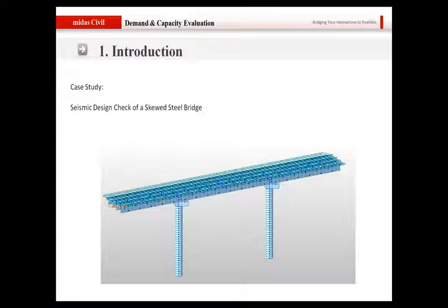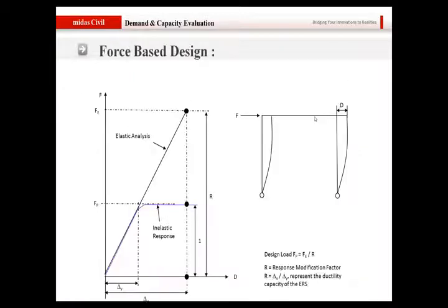For those of you who were present in the technical seminar by Ling Zhao from Michael Baker, he talked about the difference of approach between the force-based design and the displacement-based design, and he told you that seismic design is now moving from force-based design towards displacement-based design. He also talked about the different concepts of response spectrum analysis and pushover analysis and the different codal provisions for those types of analysis.